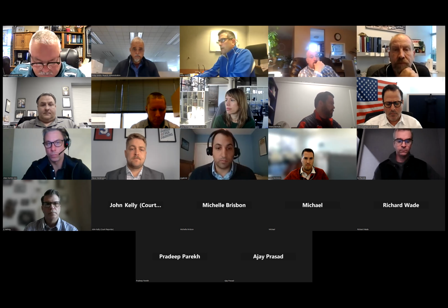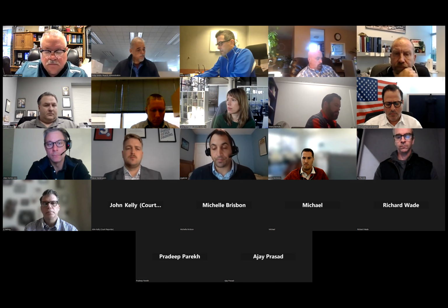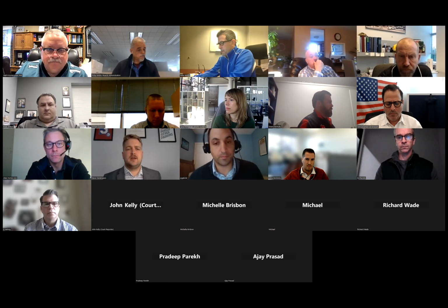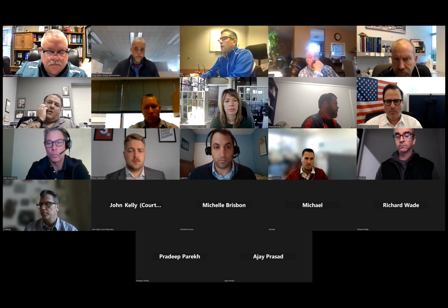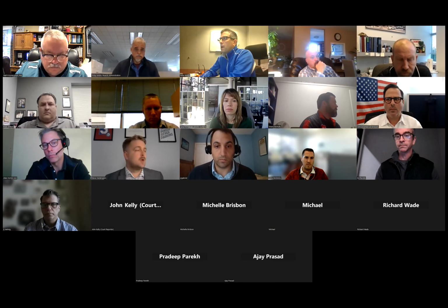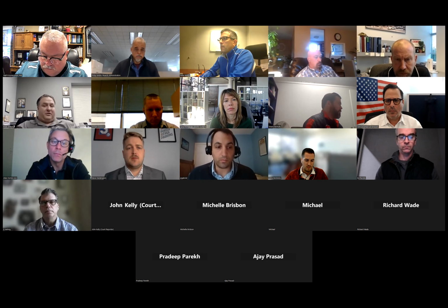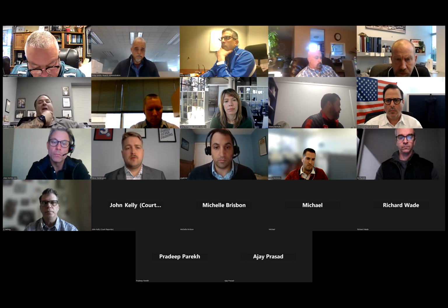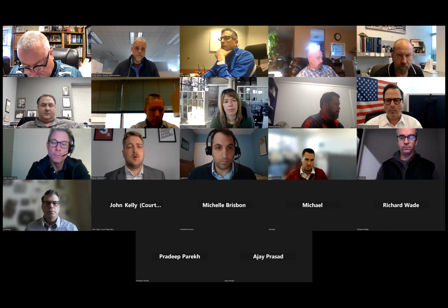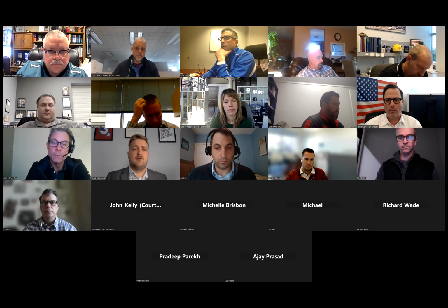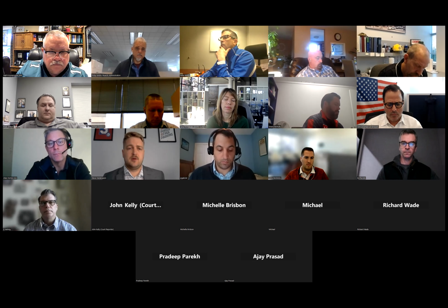Please continue. Steve, if you could jump in and start talking about the design intent, if you need me to pull up anything, I'm happy to pull it up. Thanks, Paul. To identify myself, Steve Heidengren, plumbing design lead for the project with Jarrell Spellman Falls. Excuse me, sir, this is the court reporter. Could I ask you to slow down just a little bit? Yes, sir. Apologies. So the existing building has a tray green roof system and scupper drains that allow for overflow drainage to leave the roof. The existing building only has a standard storm drain system within the building with no overflow leaders. The building was built under the 2004 Philadelphia Plumbing Code prior to our transition to the 2018 Philadelphia Plumbing Code that now applies.